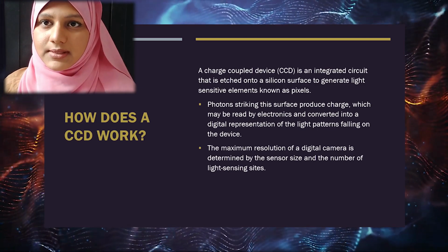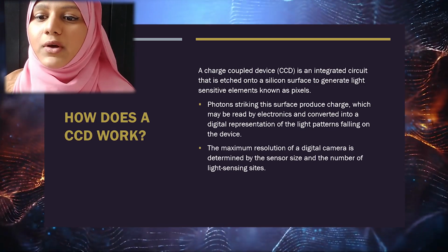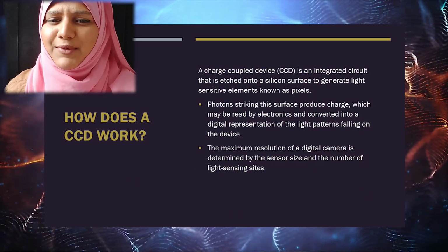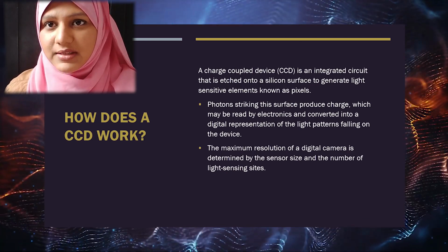Advantages and disadvantages of CCD sensor. Advantages: number 1, because of the increased surface area, there is more sensitivity and less noise. Number 2, due to the simpler structure, there are fewer faulty pixels. Number 3, the central A/D converter improves the visual uniformity. Disadvantages: number 1, as only one central A/D converter digitizes, the readout is slower. Number 2, the camera as a whole consumes more energy. Number 3, due to the increased circuitry required and more sophisticated camera layouts, they are more expensive.